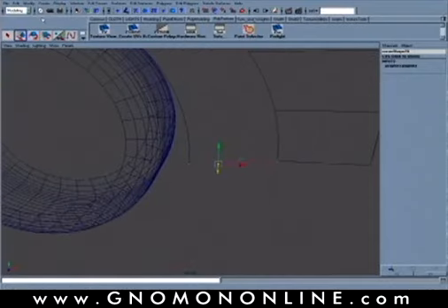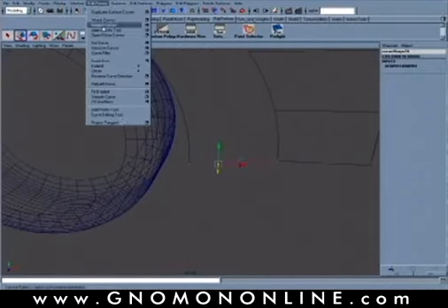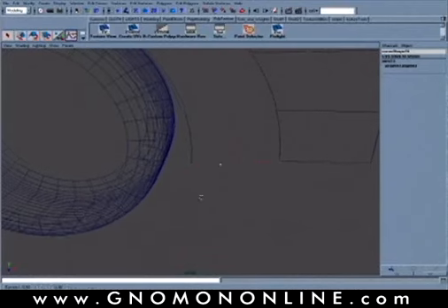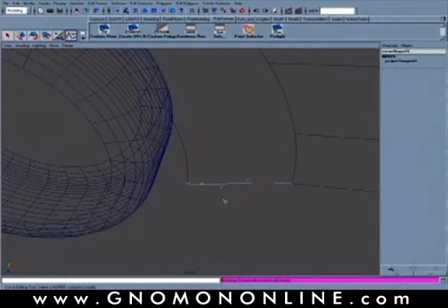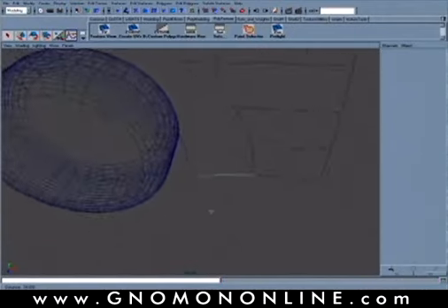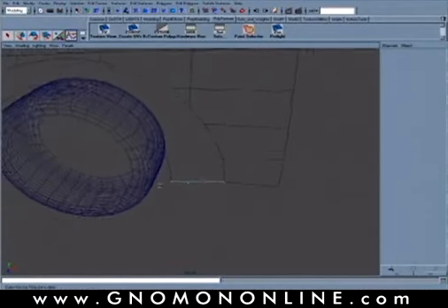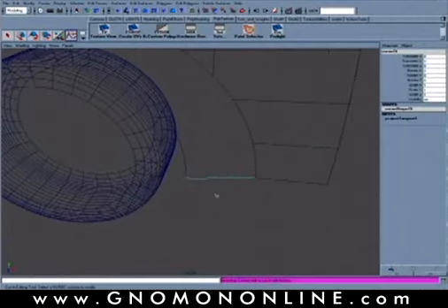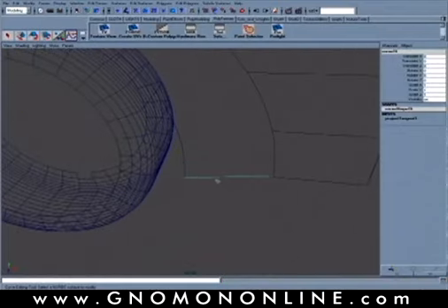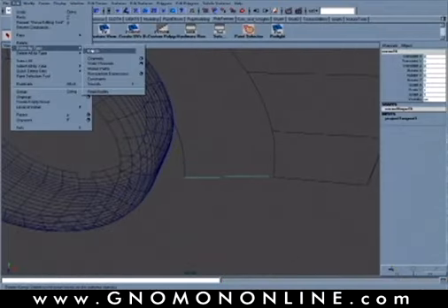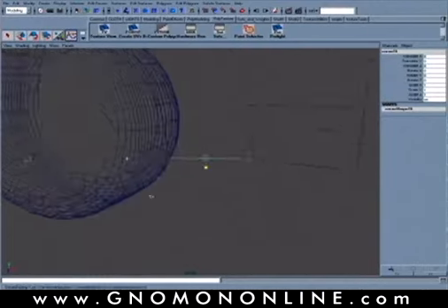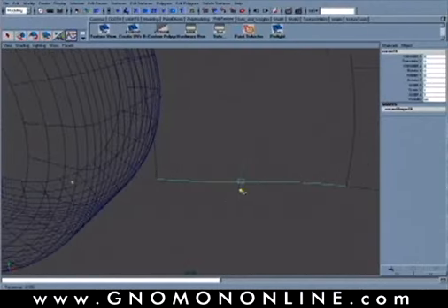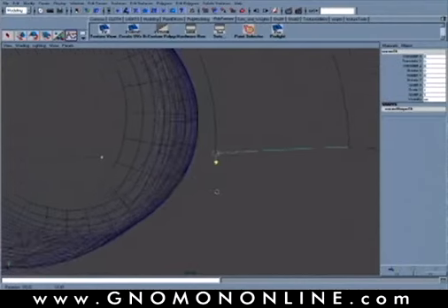Or else you may want to use your curve editing tool again. So we can go into curve edit. And one of the downsides you'll see is I was getting an error that it won't work because we have history on. So you'd actually have to void your history at this point, meaning the history between the tangency that we had there. So you can do that if you want to use the curve editing tool. Kind of a bummer that they don't work together. So if I do that, delete history, I will be able to get back to the control of using the curve editing tool. But they can't coexist with project tangent. So you just have to find a little workaround for that.